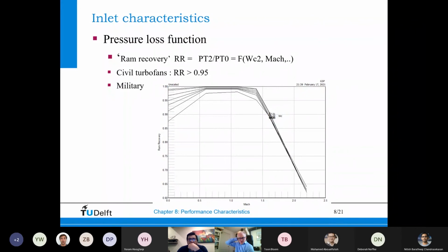If you remember what the F-16 looks like, with a big inlet under its fuselage, somewhere below the cockpit, with a sharp inlet lip, that is to maintain some reasonable efficiency at supersonic speeds in terms of the supersonic aerodynamics there.